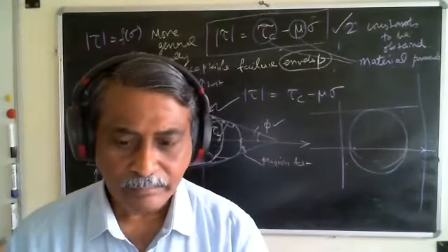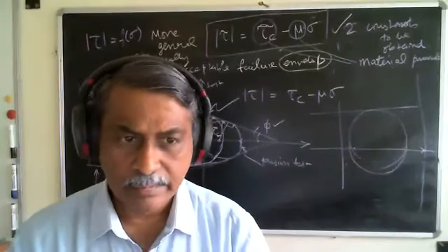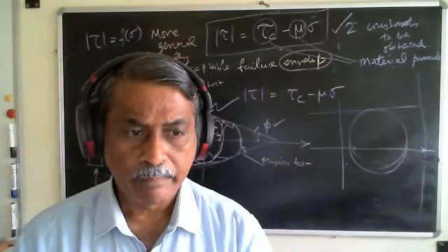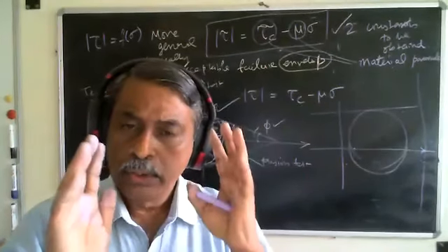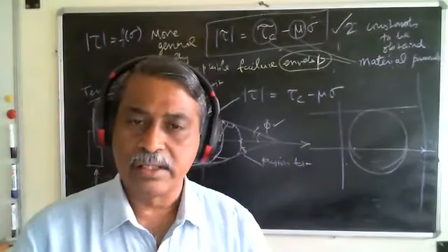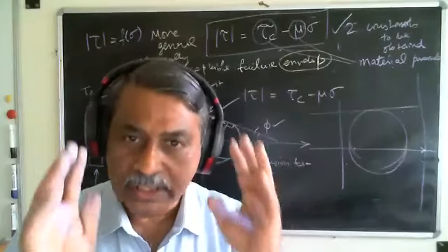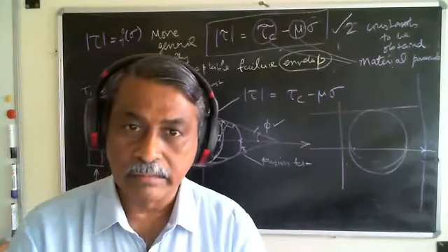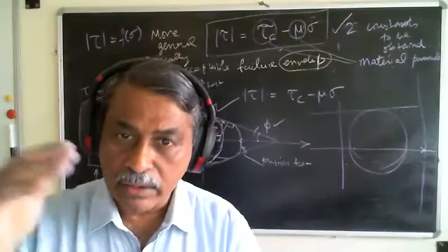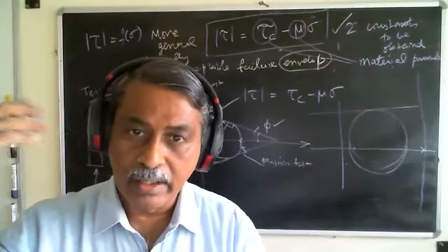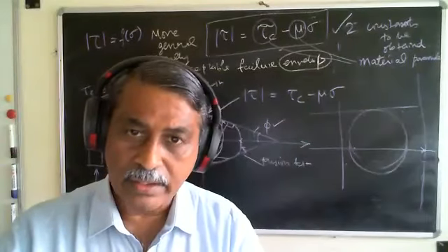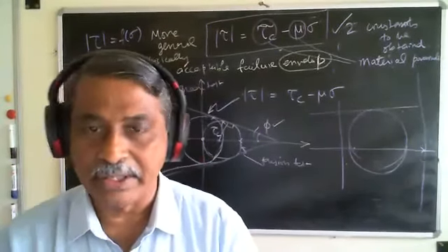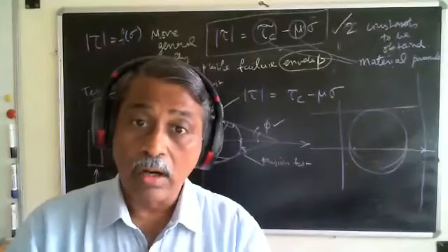Any questions so far? Okay. So basically what do we do? If it is a single material constant, apply a known stress state where you can increase the magnitude of the stress. As you increase the magnitude of stress, at a particular point of the application of stress, it fails. Failing could be yielding or a separation, or a combination of the two.